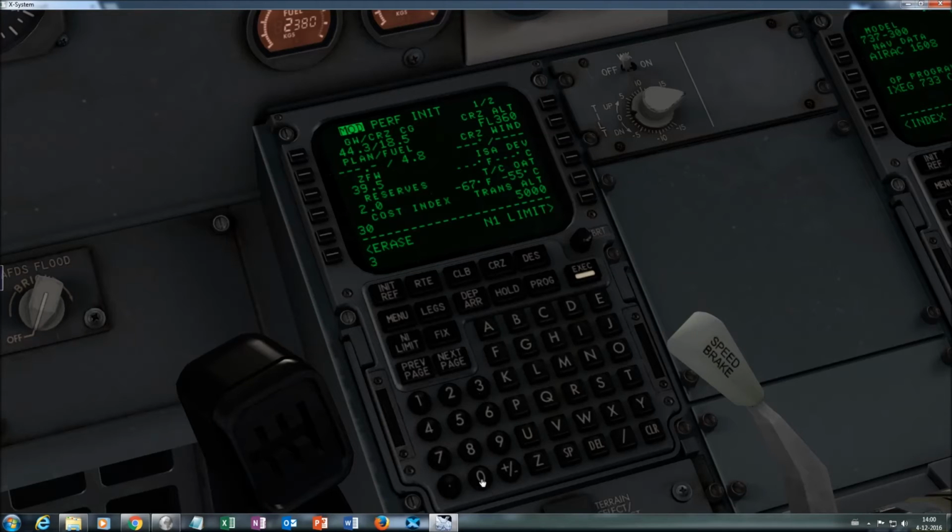It's not in here, I think. Well, I'll just look up transition altitude 3,000 feet in Amsterdam. So let's dial that in. And again, execute, because now the flight management computer knows that all the input we gave is correct and we want it to work with it. That's why you execute it. If you don't execute it, it doesn't work.